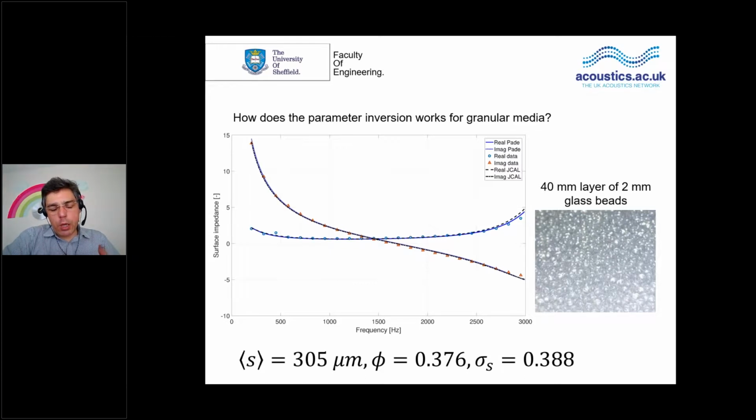The suction pressure is inversely proportional to the pore size. So you would know the proportion of pores of different size and radius from the suction pressure data. There is a paper I can send you a link to, or put in this folder, that you can read about.